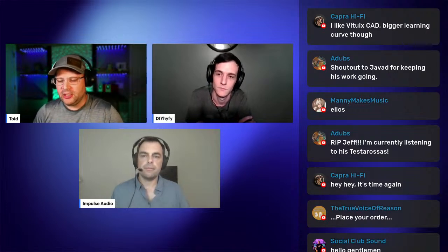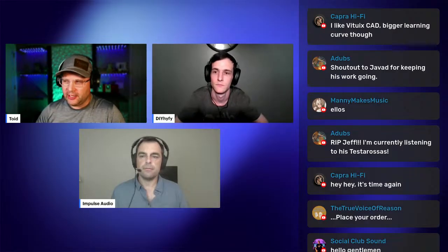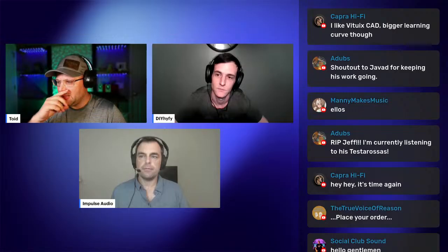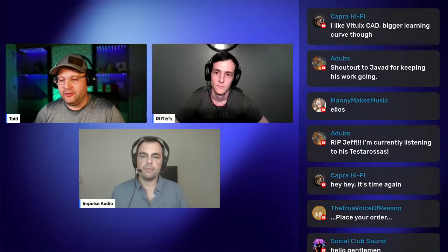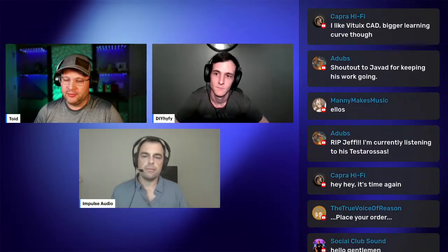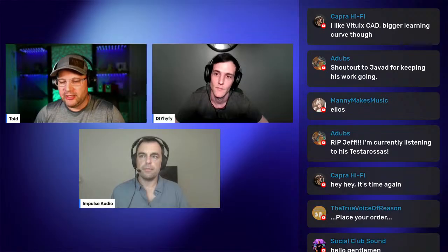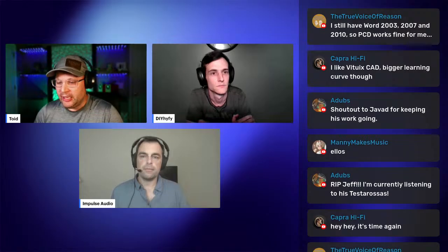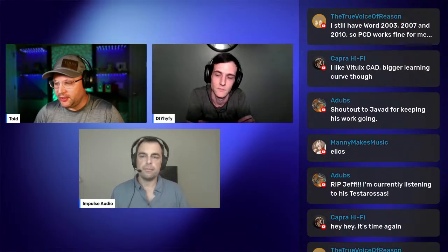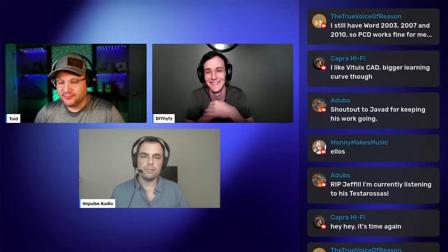And not to mention, we don't want to get too far down the rabbit hole for people that are still learning, but it doesn't take into account things like the offset of the drivers, which is another big issue. So your phasing, all those issues, you need to take those all into account to make a good crossover point. But you're absolutely right. I still think we should do a build off with a pre-designed crossover board.